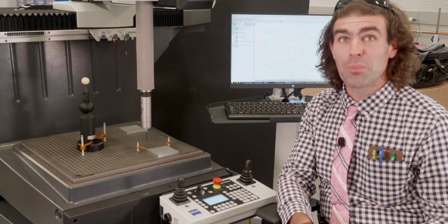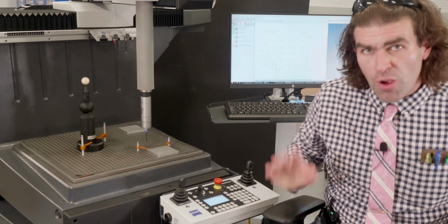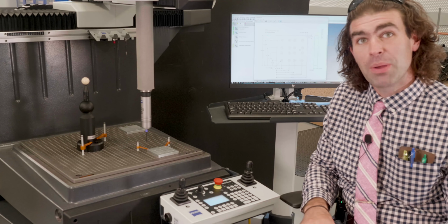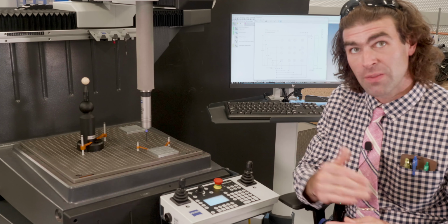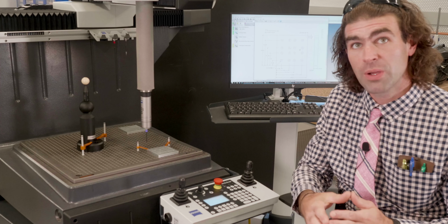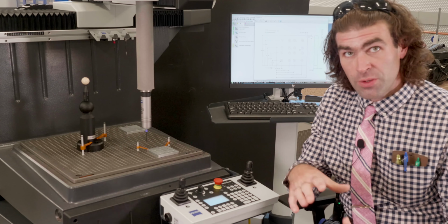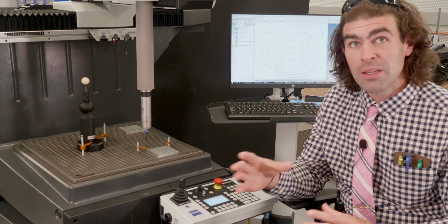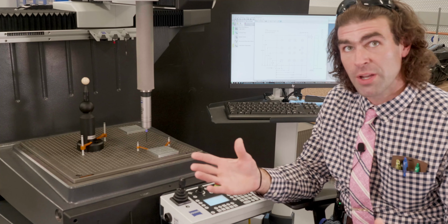It gets pretty repetitive. So the first thing we'll want to do is open our program that has the basic alignment. We'll go through and check and make sure basic alignment's still good, make sure our clearance planes still look good, okay? The cool thing about Calypso is that any features you use in your alignment will also get used in your characteristics and features when you're running the program.